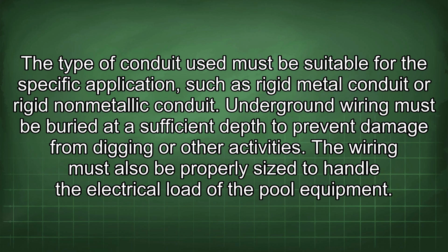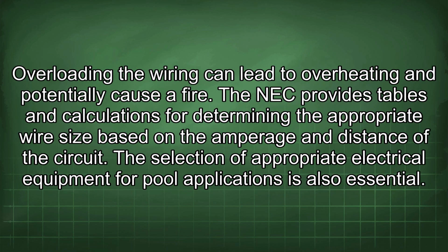The wiring must also be properly sized to handle the electrical load of the pool equipment. Overloading the wiring can lead to overheating and potentially cause a fire. The NEC provides tables and calculations for determining the appropriate wire size based on the amperage and distance of the circuit. The selection of appropriate electrical equipment for pool applications is also essential.